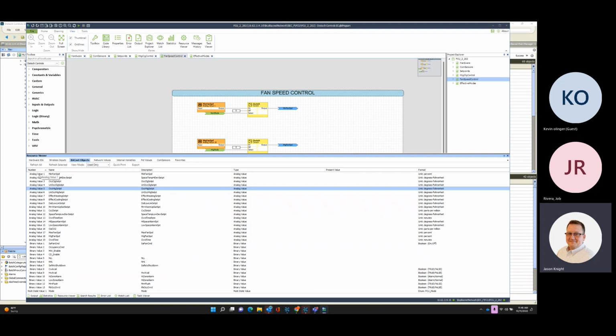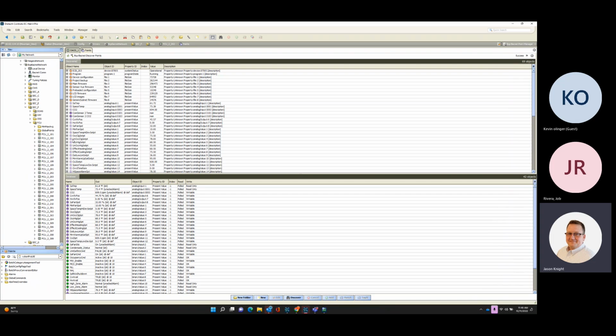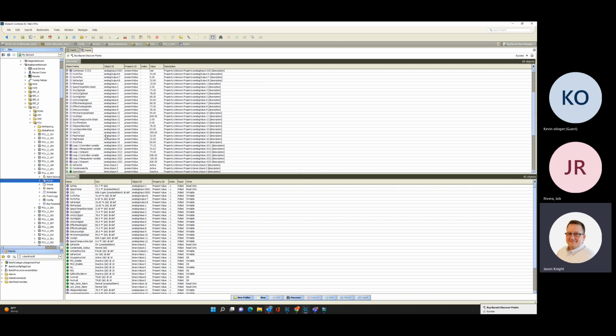I have all these AVs, analog values, and they're basically BACnet objects that we pull from the local programmable logic controller that's up in the ceiling that's mounted on your equipment. We take these values and we learn them in Niagara. So for instance, here's the object that I discovered for FanCoil 202. I double click on the points folder, I do a discover, and then I read all those analog values, Boolean values, enumerated values, and they all get discovered and pulled up into your building controller.